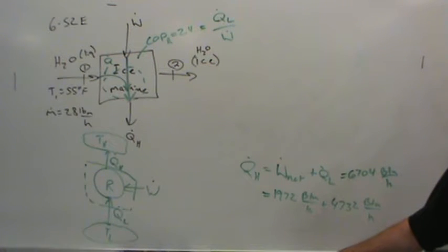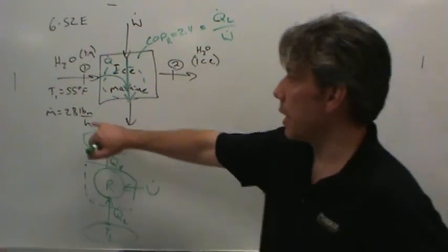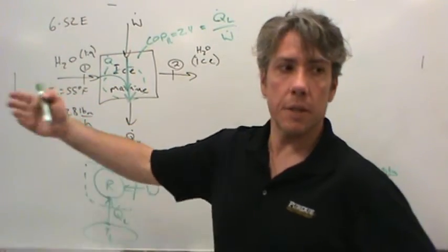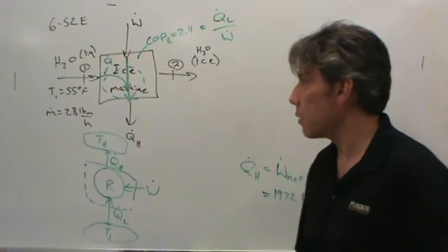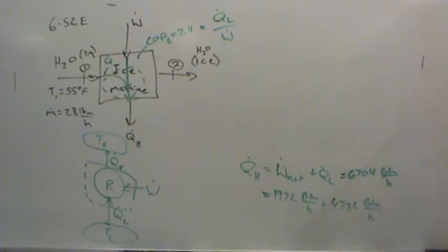288,000, okay. So you have to pull 288,000 BTUs out of a ton of water if you want to freeze it. Now, if it's at a temperature above 32, like this was, well then that's even more energy you have to pull out of it. So, anyway, where was I going with this? Oh, where I was going is that